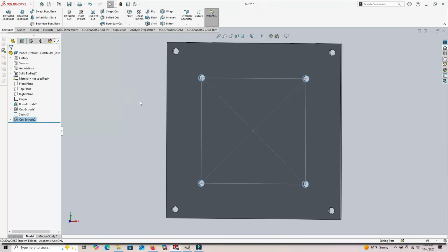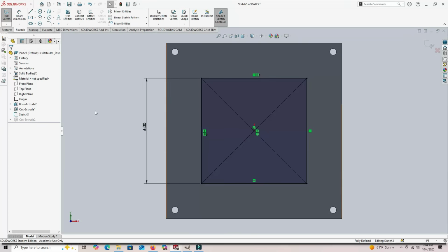There we go. And let's say that instead of wherever this is, this would be 2 inches in from each side. If I had wanted them to be 1/2 inch in from each side, I would just make this rectangle, the second center rectangle, be the appropriate dimensions. So I'm going to go in here and edit this sketch.